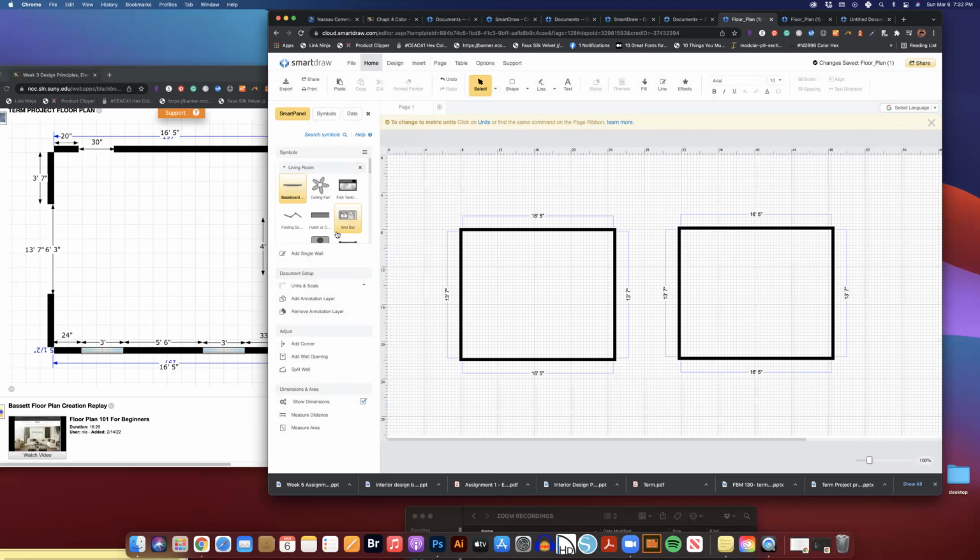So I'm going to repeat the process again, and I'm going to just close this for now because we need our space, our wall opening. So I'm going to pull out the wall opening. Again, if you simply click it, you can type 30 inches. This should be 1 foot 8 inches because that would equal 20 inches. So that completes this wall. We have a 30-inch opening.